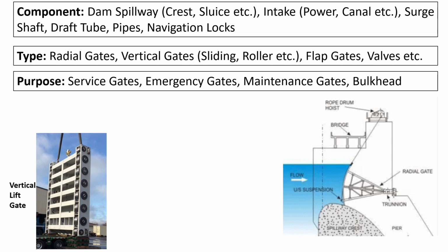Most of the times, gates are fabricated in pieces. They are assembled at the site due to size constraints of plates and so on. Generally around 3 meters height pieces come as single piece. While lifting and placing, these are placed in pieces at the positions. Sometimes, there is requirement of having a single gate instead of pieces. These are called bulkhead gate. That means all the pieces are joined together. Let us say 3 pieces of 3 meters are joined together. So overall it acts as one piece.